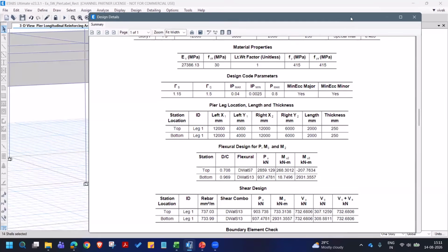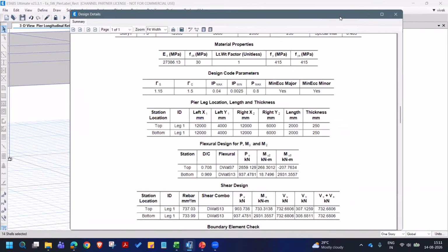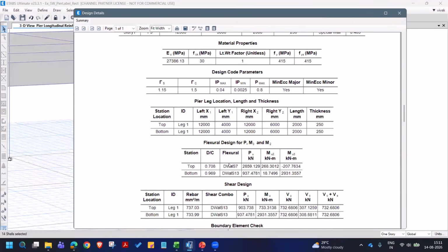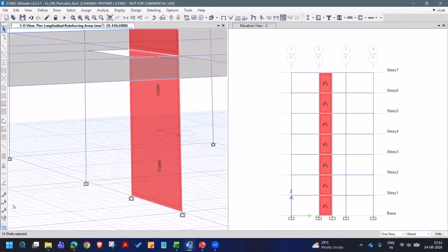Right? Previously it was around 10,300 or something. But anyway, when you work with the reinforcement bars and how we are providing reinforcement, basically the boundary element enhancement of the reinforcement at the ends significantly increases the cross-sectional moment capacity, and that benefit you will get in the output as well. This is how we use this general reinforcing for the wall.